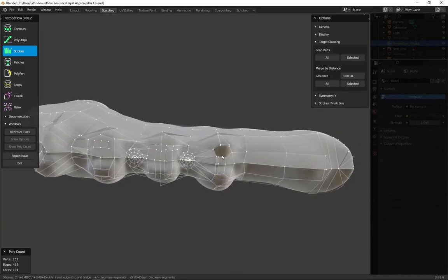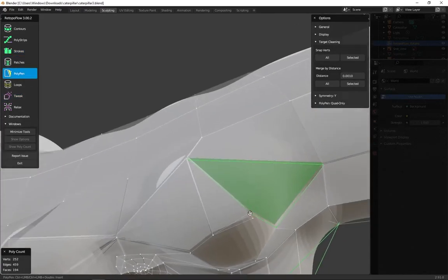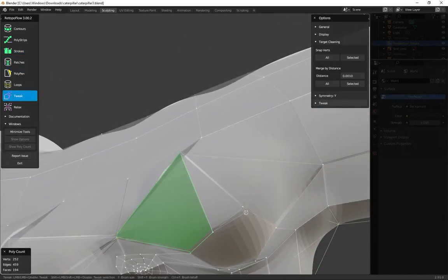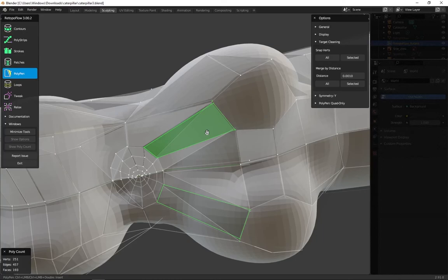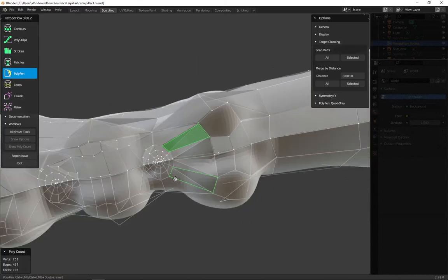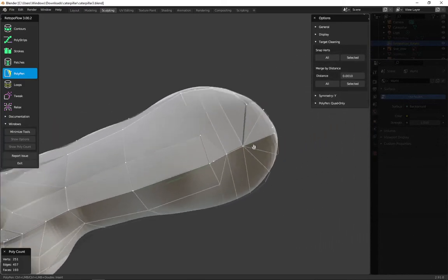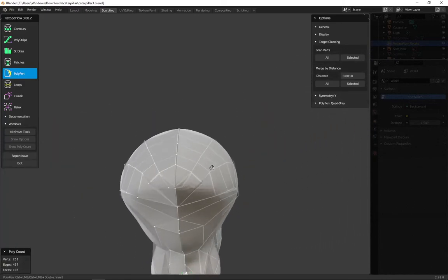I want to enclose the whole body as best as I can, make it manifold, a closed model. So the tail's closed up. The legs, for the most part, are closed. I think I still saw some openings. So technically this model isn't manifold yet.